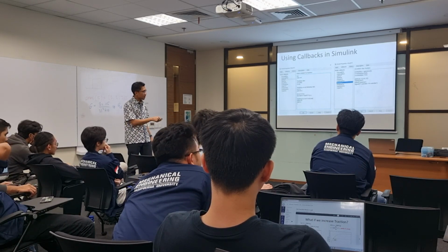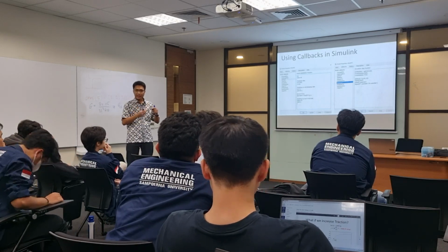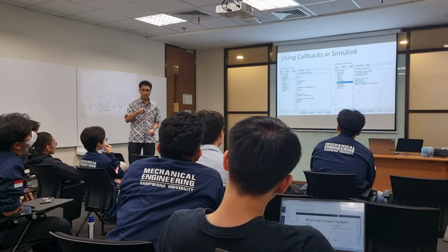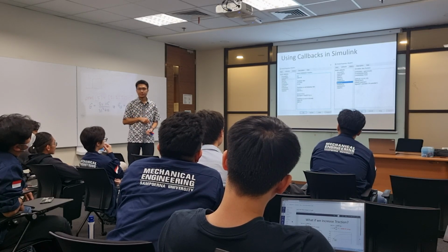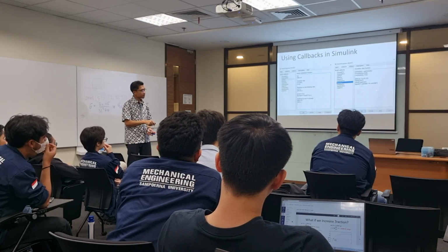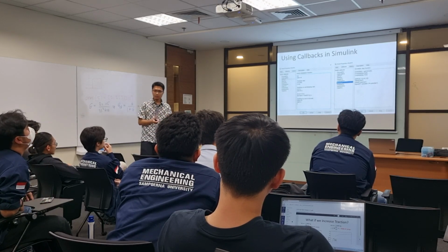So when you set all of the M in here, all variable M in your Simulink change directly. You don't have to click all of the blocks, okay? And then you can also do another function after the simulation stop.